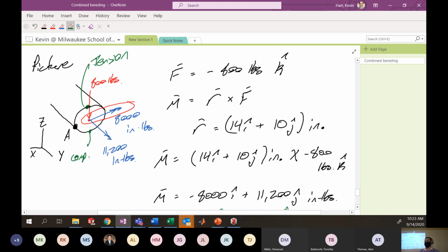All right, so if we think about curving this particular piece, that's what's going to happen. We're compressing the bottom side and pulling the top side. That means that the neutral axis of bending for this applied moment is right across the center of this cross section. And that's a key point about bending moments: when you have a bending moment in the cross section of your piece, the neutral axis will be along the same line as the double arrow. So here, this is your neutral axis for this 8,000 inch-pound bending moment.